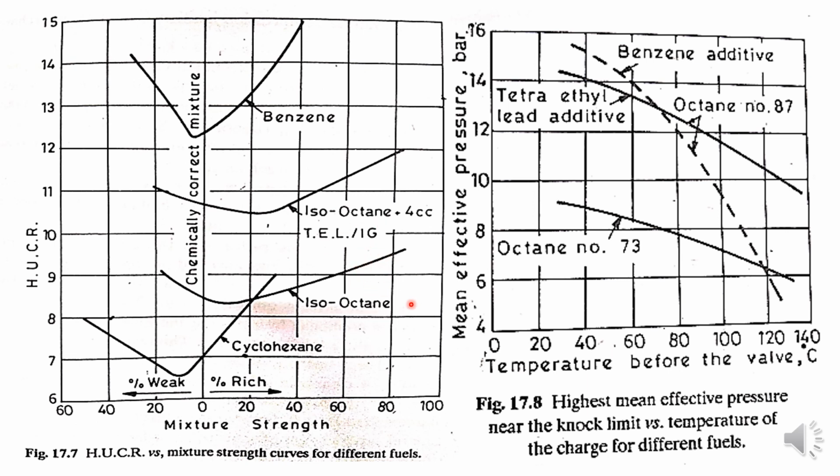The knocking limit of an SI engine is also affected by the ignition timing. Ignition timing is affected, and with the thermal load of the engine, high intake pressure and temperature, the ignition must also be retarded. So these are the things we have to take care of regarding supercharging limits for your SI engine. In general, we can say that a supercharging pressure in the order of 1.3 to 1.5 bar can be used for an SI engine, with 30 to 50% supercharging.